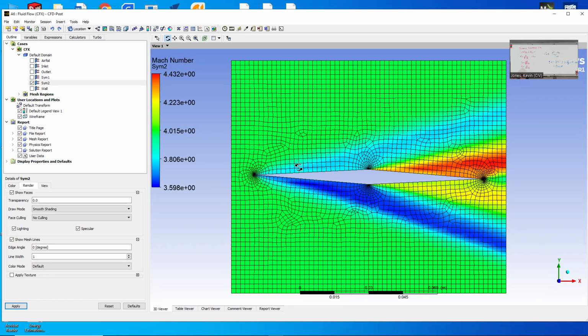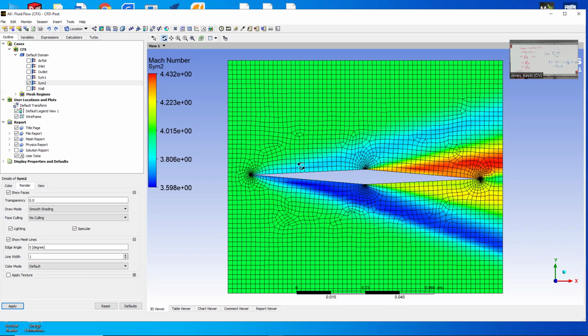We haven't really talked about, well, we talked really briefly. Remember the term upwinding when we first introduced the idea of the characteristics, and we said you can't use the information outside of these two characteristics to influence a point. So they did this upwinding thing, and they switch to upwinding when they get right around the shock, which lowers the order of the calculation a little bit. Everywhere else, they're using some kind of higher order scheme. So anyway, the shock is super smeared because the cells are big.